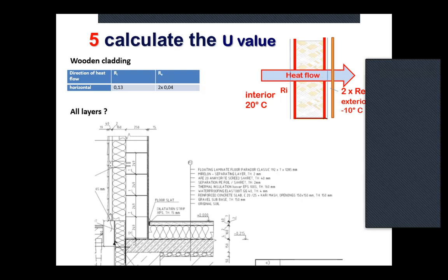If the capillary breaking area is foam glass, then of course you calculate foam glass, because at the same time it's also thermal insulation. That is good to mention. But if it is foam glass and for some reason there is gravel again underneath, you don't calculate the gravel, because it doesn't have any insulating effect anyway. Even though it's a capillary breaking area, it can be very moist, so it's not added into the calculation.